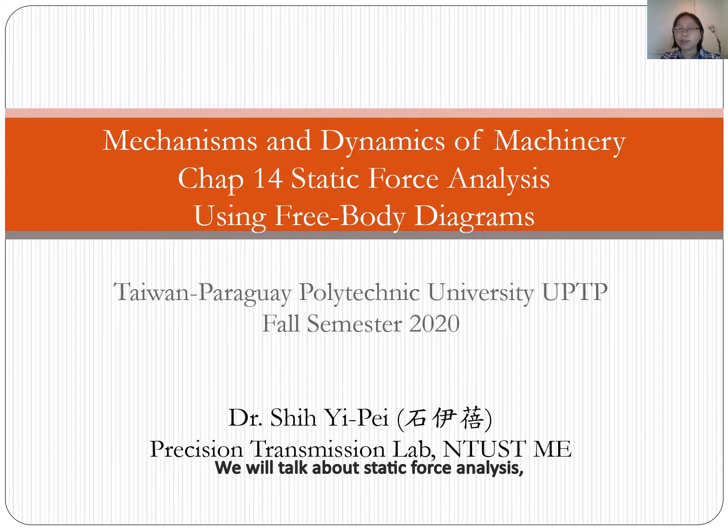We will talk about static force analysis. There are two methods used in this course: free body diagrams and the conservation of power. This slide will show you how to use the method of free body diagrams to figure out all the forces acting on the mechanism under an external force or torque.